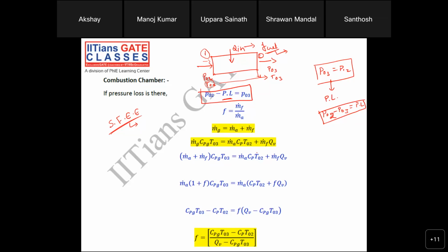You have to remember this part. The stagnation temperature we are talking about is not an actual quantity; these are all defined quantities. The actual quantities are your static quantities. Static pressure and static temperature are the actual pressure and temperature at that particular point. But at the same point, we can define these other quantities.